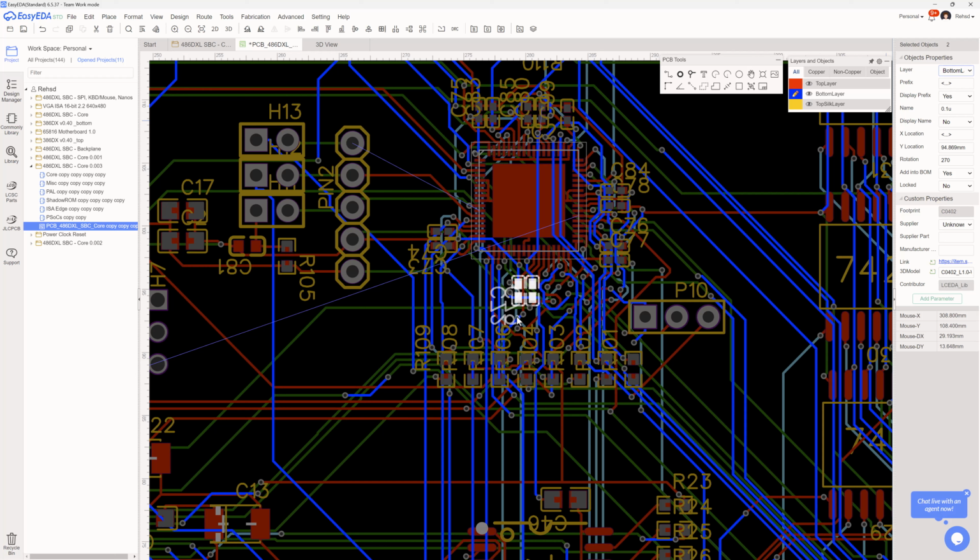And while it's doing that, because this will take a second, I will just mention EasyEDA is a pretty poor PCB design tool once you go to inner planes. Every time I want to really work on the board, I've got to go in and get rid of the inner ground and VCC planes. Otherwise it does what you're seeing here. It just struggles. I made a change and it takes 30 seconds to make one simple little change, like moving these from the back to the top. I'm sure the answer from EasyEDA is, you should now be using the Pro version. Yeah, sure.